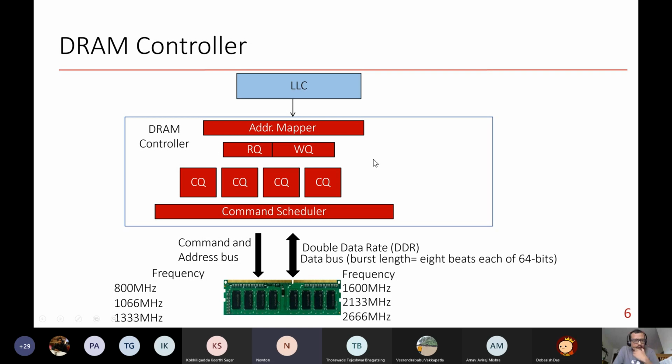I have a basic question. When you say column, does it generally mean a set of 8 bits? Yes, it will be 8 bits. When we are accessing DRAM, one bit is stored in one capacitor, right? It depends. I can design a different notion of column, but for the sake of simplicity, let's assume 8 bits.